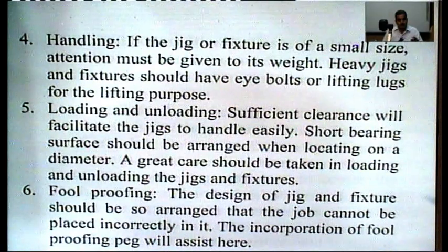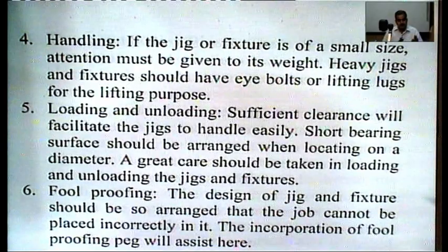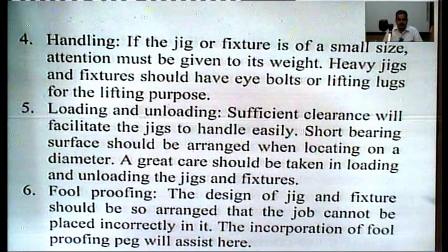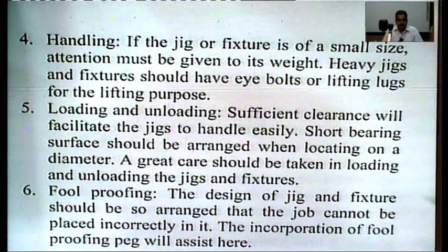The system should be such that these jigs and fixtures should not allow the job in some wrong way. The incorporation of a foolproofing peg will assist here.